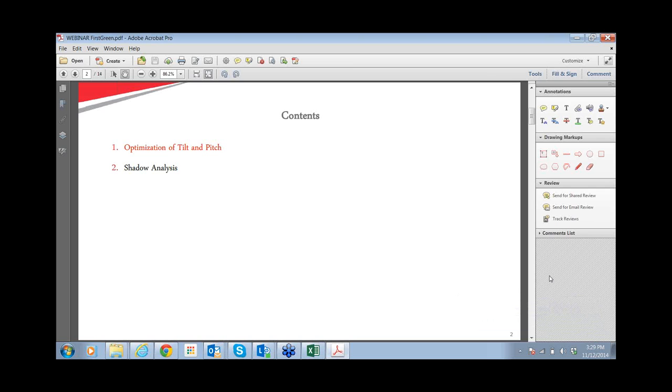So in hard strata, I can go with lesser spacing and a higher number of foundations, because foundation cost is less in hard strata, and in loose strata I will recommend going with fewer foundations with longer base spacing.